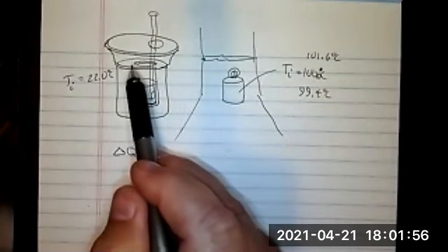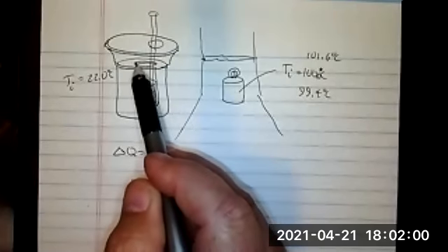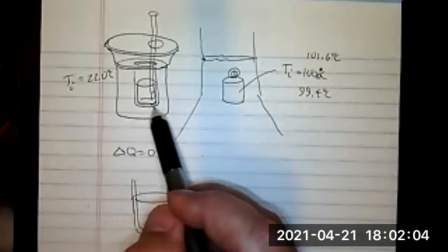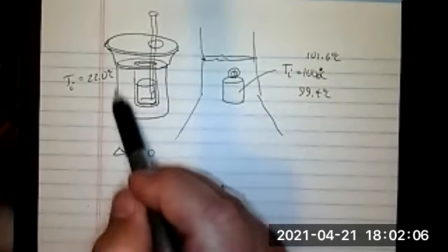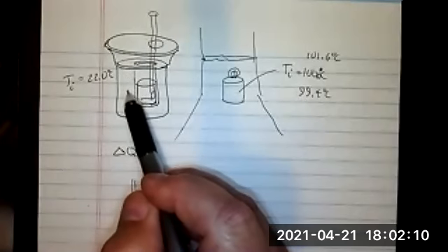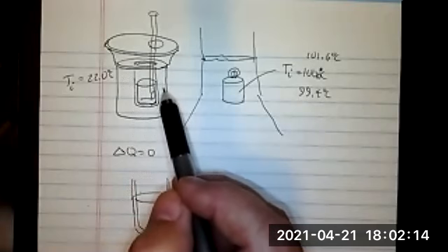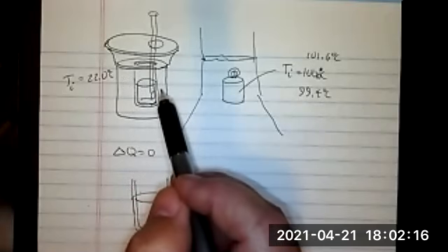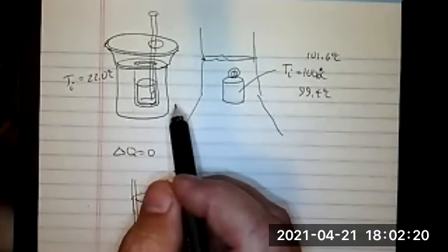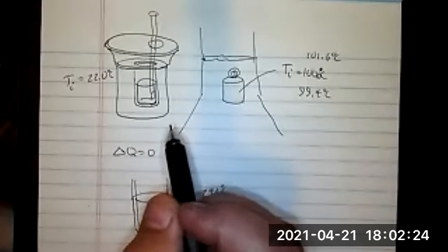And it really is. What you've done by putting this little wafer here is prevent conduction from taking place between the inner aluminum cup and the outer aluminum cup. And you've gotten rid of the ability to do convection because you actually have air trapped between the two. So you can't do conduction, and you also can't really allow much airflow within. So you're getting rid of really all the ways that heat could be transferred from this inner cup to the outer cup.